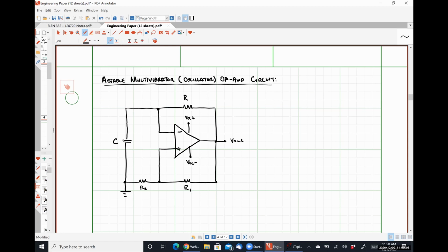So that means it oscillates back and forth between, because it's a positive feedback circuit, VCC plus and VCC minus. It's never going to settle to a specific value. There is no input voltage, meaning if you wire this up to a practical op-amp circuit and you wait, it will start ringing between VCC plus and VCC minus, and we'll see that exact same thing when we simulate it in a minute. Let's talk about what the heck is going on here, okay?